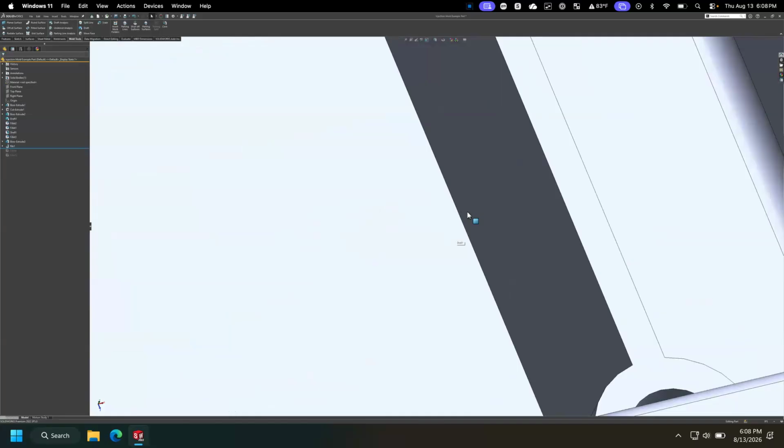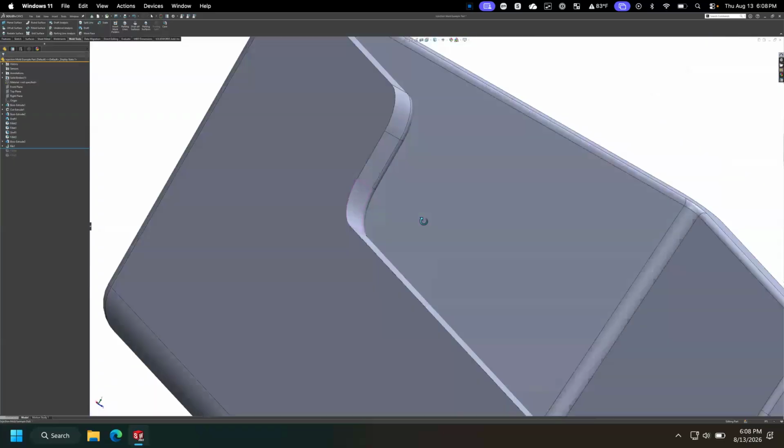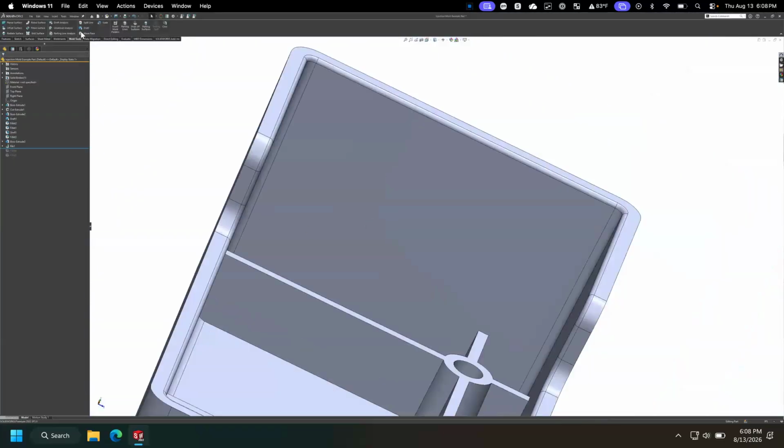There may be areas where, depending on where your parting line is, you could have a radius into an infinite sharp. If you think, oh, I'll just put the radius there, but then your parting line's right there, well, then you have a radius up to your parting line. That would be a bad design for manufacturing feature, because now you've got that really sharp, infinite sharp point on your mold. Not in this case, because he knew where his parting line was. But if I didn't, what I'm getting at is